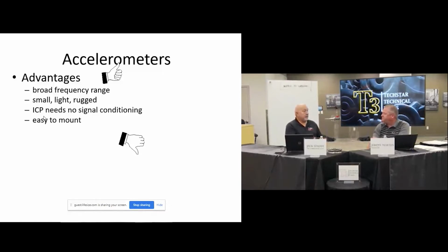We have different analyzers out there, different makes and models. Some of them will have the power start when you push the enter button to collect your data. So when you hit enter, you have to wait 4 seconds for it to settle down. Then there are other analyzers where, when you turn the analyzer on, it's already powering the accelerometer, so you don't have that settling time.